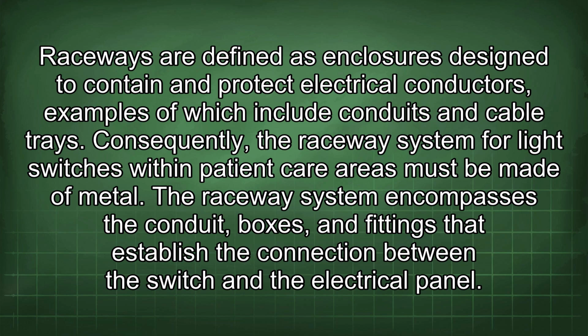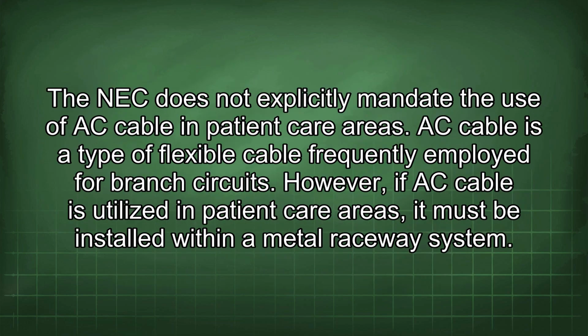Consequently, the raceway system for light switches within patient care areas must be made of metal. The raceway system encompasses the conduit, boxes, and fittings that establish the connection between the switch and the electrical panel. The NEC does not explicitly mandate the use of AC cable in patient care areas. AC cable is a type of flexible cable frequently employed for branch circuits. However, if AC cable is utilized in patient care areas, it must be installed within a metal raceway system.